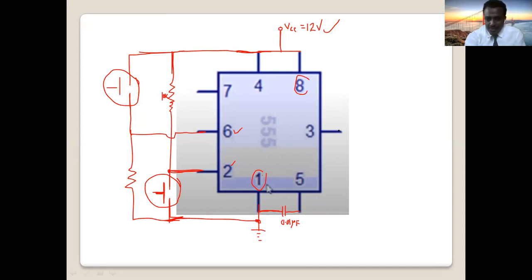So now if you connect your light emitting diode, as an example, you can connect any other device. If you connect your light here, this will be either on or off state, right? Always the timer output can be 1 or 0, the output at pin number 3. So to make it on, it needs input. To make it off, it needs another input, because both states are stable. Stable means without applying input, it remains the same. So the output remains on.